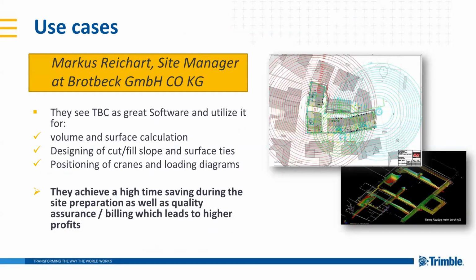I just want to come to some use cases and how our users are utilizing Business Center. We have one site manager, and that's what I've learned, for example, from him. They're using it for cranes and the loading diagrams. In the picture, you can see the circles with the different weights and the loading diagram to know on site where to position the crane and on what radius they can move what kind of weight. They're also doing volume and surface calculation. And what they really like is designing of cut fill slopes and surface ties.